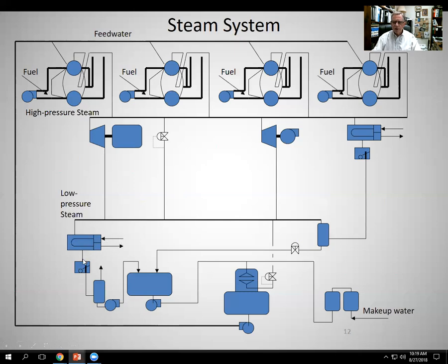The condensate comes out of this heat exchanger to a trap, and then it goes to a little condensate collection tank, a flash tank. And this arrow indicates that this tank operates at atmospheric pressure. So we have a little bit of flash steam here that we are venting to atmosphere. So we're going to let that escape from the system.